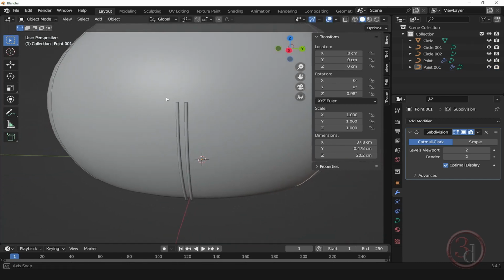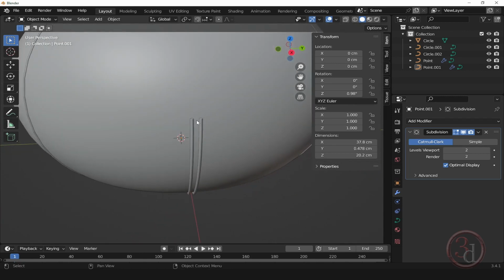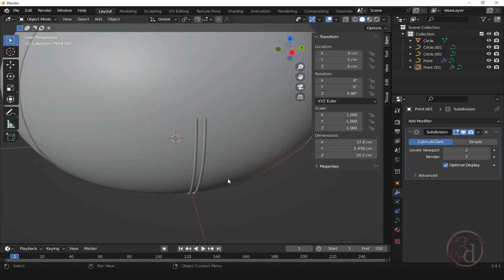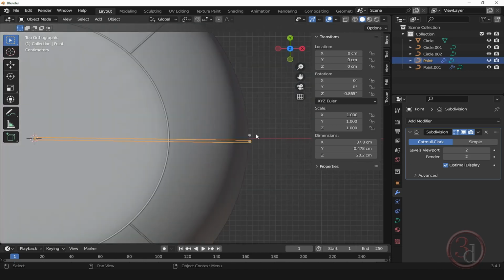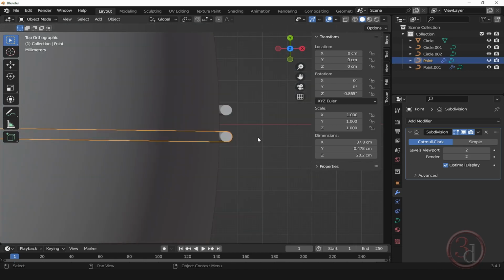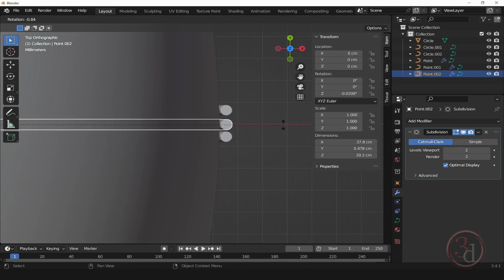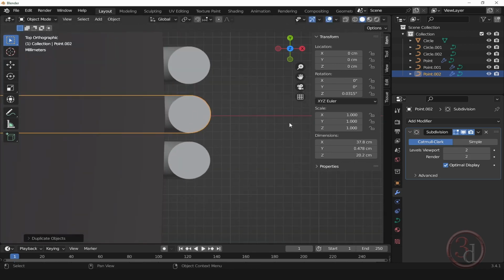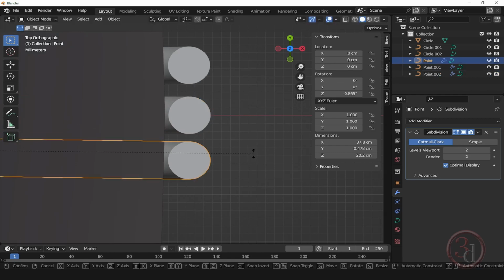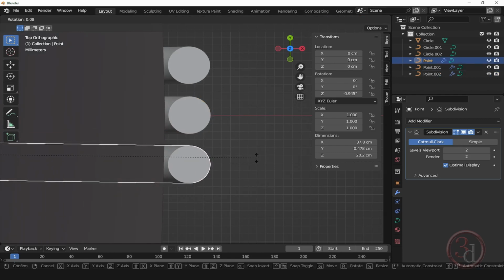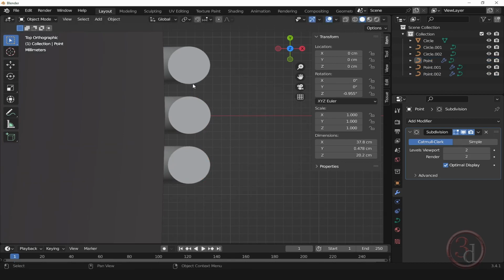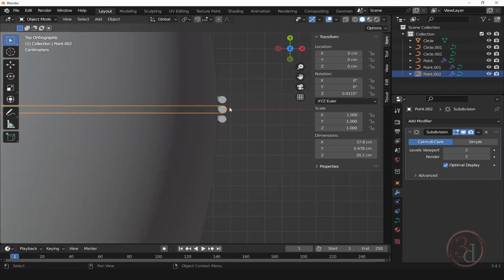So I have 2 copies of it, and now I need to create a rod in the center that will be straight going down. Okay, so I can duplicate this one, go to the top view, and I will press Shift D this time to duplicate, and press R to rotate, and then just bring this in the center. Okay, this is in the center, and let me bring it away just a little bit just to find almost similar gap. Now this one I will modify it.